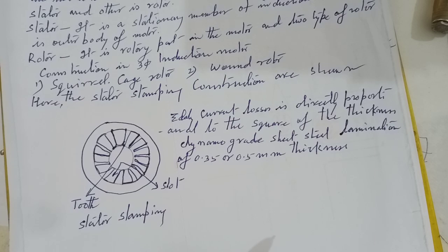The rotor slots are generally skewed by a certain angle with the shaft so as to reduce magnetic noise, to produce more uniform torque, and to prevent possible magnetic locking of the rotor with the stator.